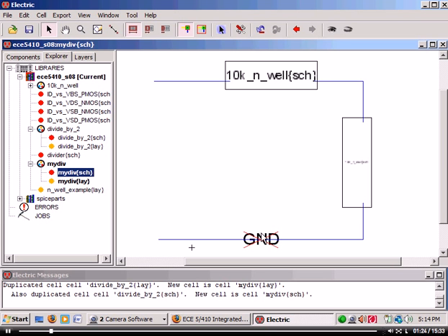They're simply node names. I named the wires, which is useful in Spice. And by the way, the most useful thing in troubleshooting when it doesn't work is to look at the netlist. Because if you can't see node 1 connected to node 1 where it should be, then you know there's an issue. So look at that text. That's why I'm going through so slow and showing you step by step how to look at the netlist. I'm doing that on purpose because I don't want you to be one of the designers that go, my tool isn't working, what do I do? Who do I call? I want you to know, okay, it's not working, what's it doing wrong?